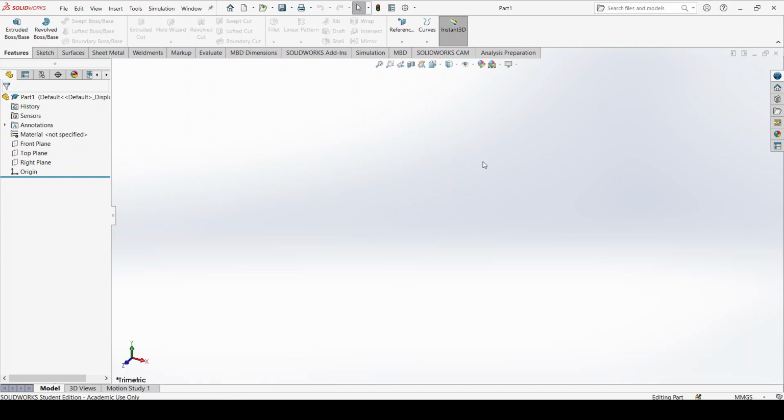Anyhow, let's start with the drawing itself. And as we can see, we are only looking at a section view. How do we know that it is rotational symmetric? Because we have a center line in the middle.